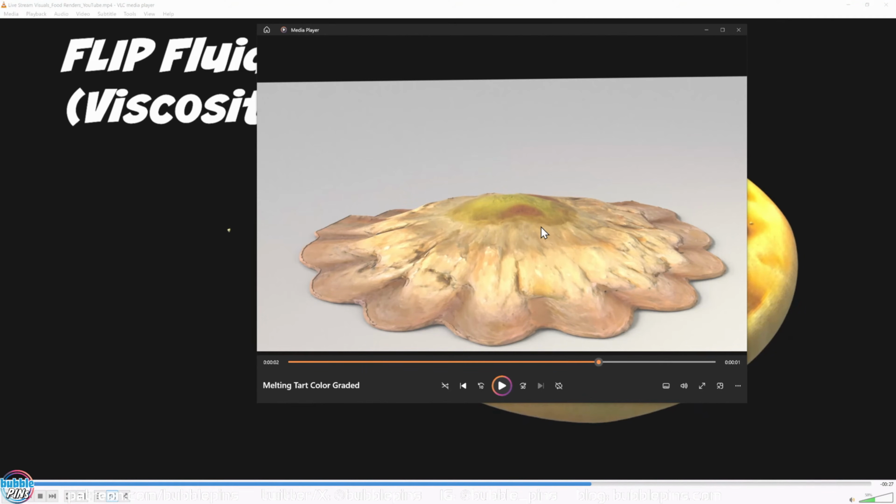You can see that it starts to, and I'm trying to hide it using the camera angle so you don't see it at the back over here, but it's starting to deform. It's starting to suck itself back in. And that's because of the flip fluids. As it melts downwards, the particles are getting really close to each other and the point deform is getting very confused and it doesn't know how to transfer. It's getting confused between the top flip particles and the bottom flip particles and doesn't know which one's which and how to transfer that motion onto the geometry.